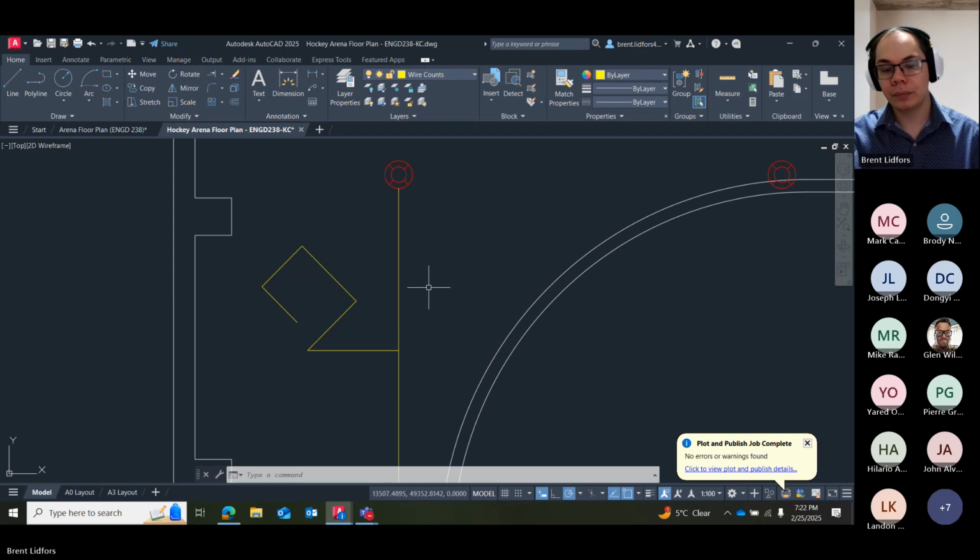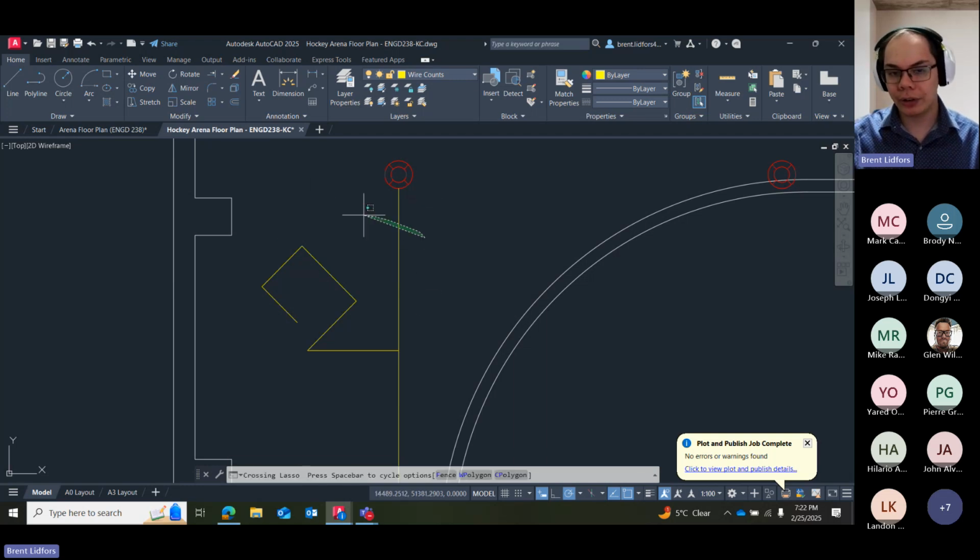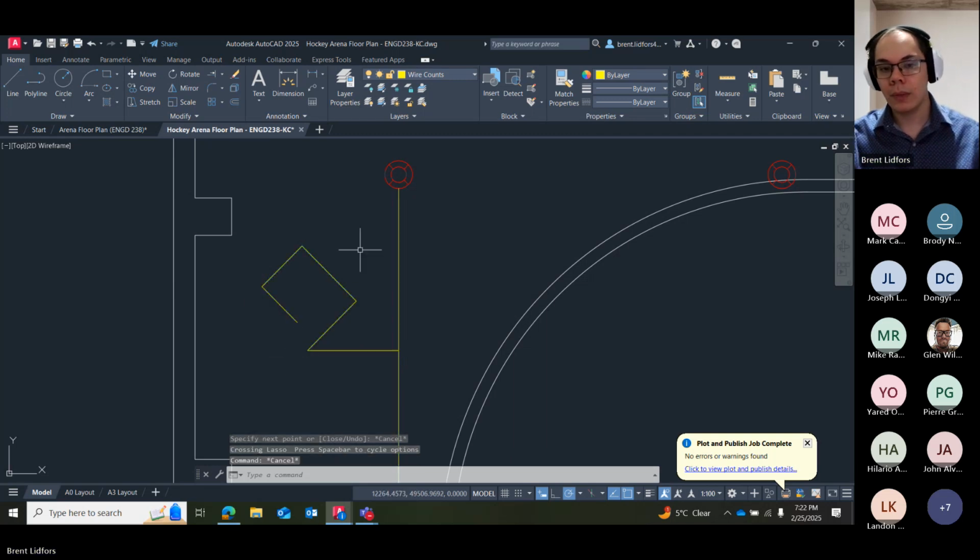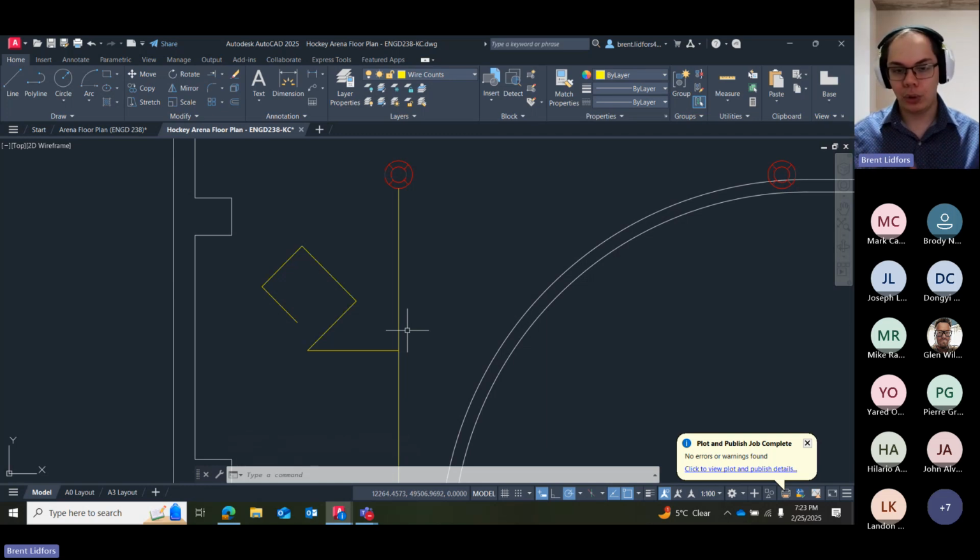It's just not practical for anyone to be building and bending conduit to such weird, precise angles. So they're generally standardized to 90 degrees or 45 degrees. So our conduit lines in our drawing should reflect that. They're also going to be always 90 degrees or 45 degrees to the actual walls of the building.